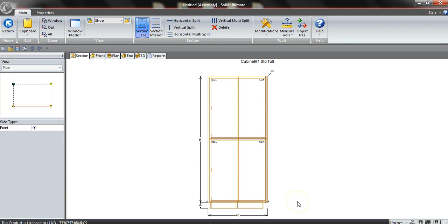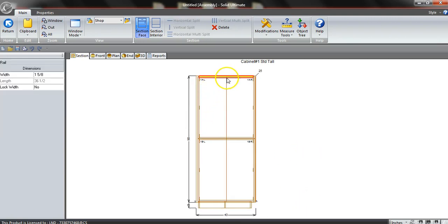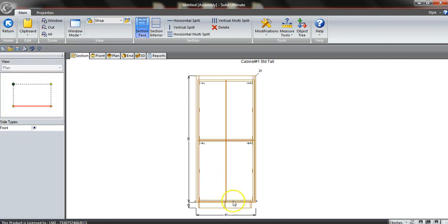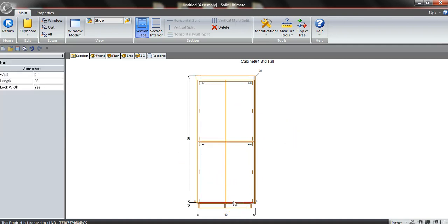And a lot of people like split up their window. I don't. I don't like clutter. So what I do is our top rail, generally 4 inches. Middle rail is going to go away. Side rails for a fridge cabinet, usually 2. 2, already was the 2. Why did I do that? This one, we're just going to delete that. Delete button. Get rid of that.